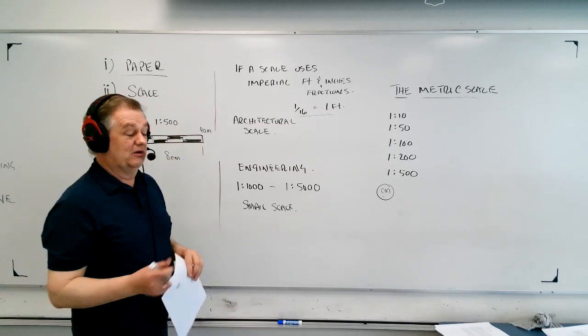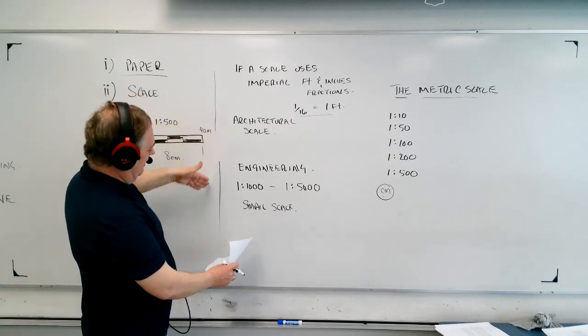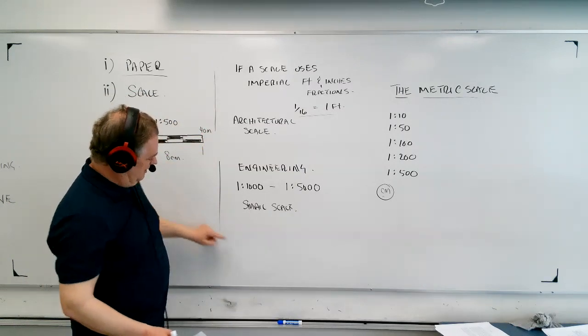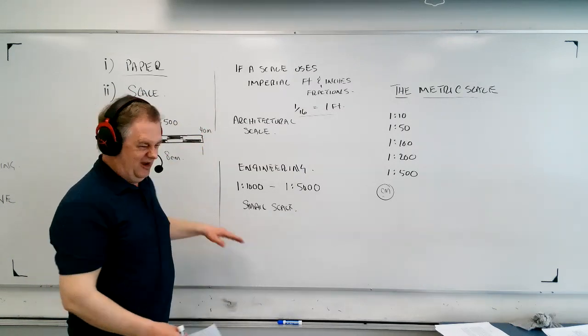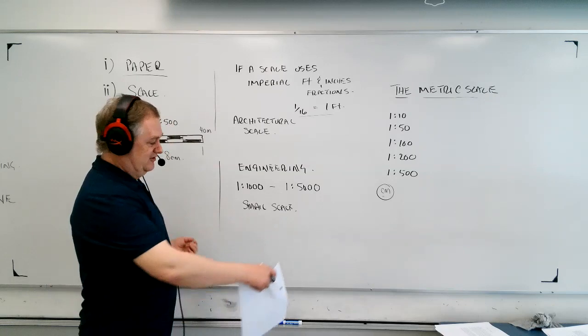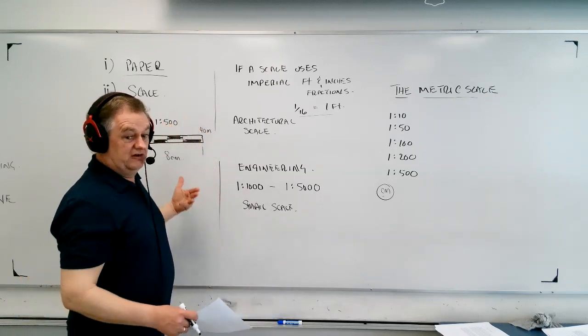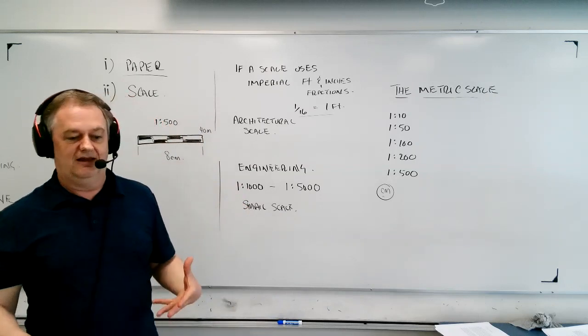So now I can take my ruler and I can measure diagonally. I want to say, okay, I'm going to cut a trench from here to here, and I'm going to lay some cable in it. How much cable will that take? Well, you can just measure how many centimeters it is, run it through, and you know your scale is accurate. We call that scaling the print.